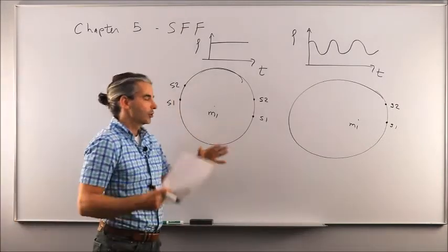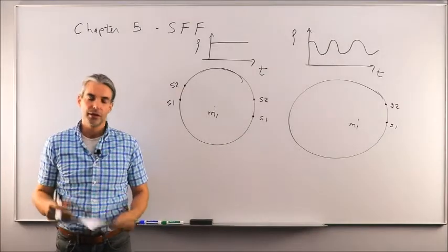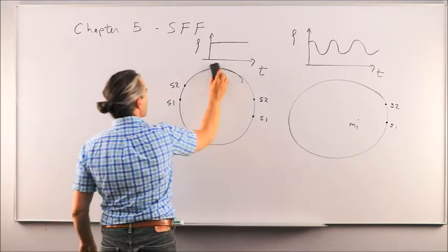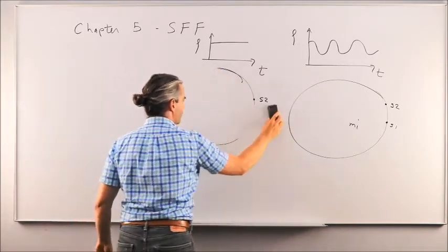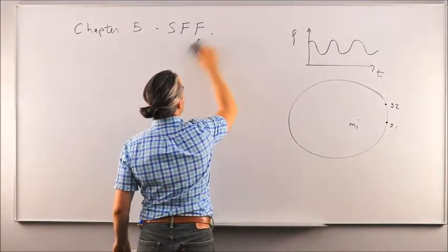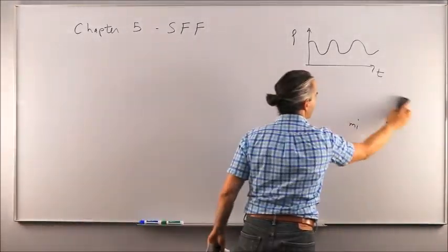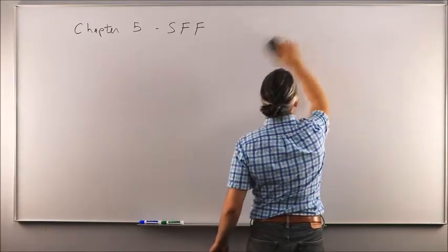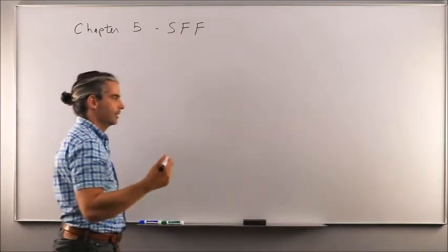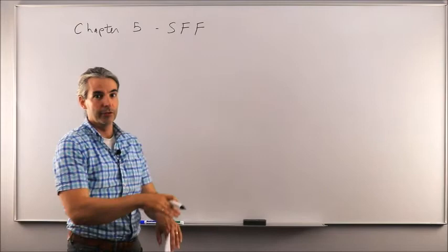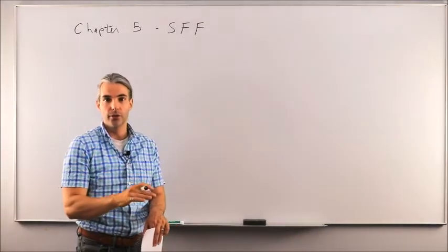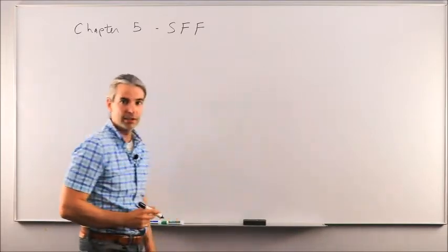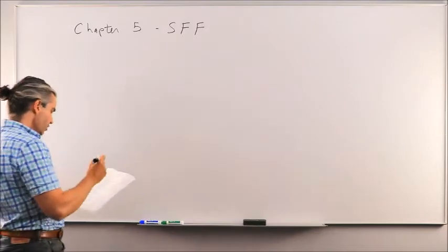So those are the two most fundamental spacecraft formation flying scenarios we can think of, but in practice, this is not how things typically happen because we're going to look at relative motion from an arbitrary direction. So you could have one spacecraft orbiting along its orbit and then another spacecraft tracking that target spacecraft closely, yet along a different orbit, which could be on a different orbital plane, such that the relative motion would happen in X, Y, Z of the ECI reference frame, and would not be one of these two very simplistic situations, okay?